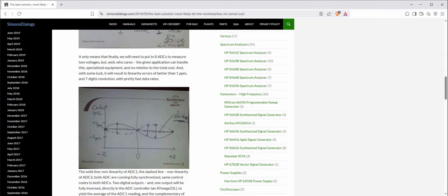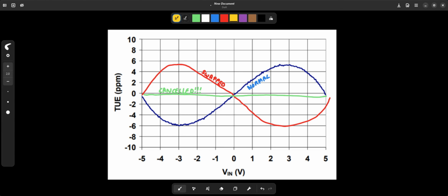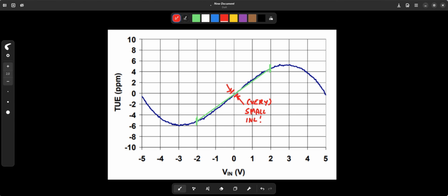Unsurprisingly, this idea has already been proposed in an old blog article. It took me long enough to realize that the idea wouldn't work, however; the errors would not cancel out like intended, but add up, resulting in no compensation at all. Jaromir's proposed solution was to limit the input range of the ADC, so the DAC output range was scaled to the flattest portion of the INL.